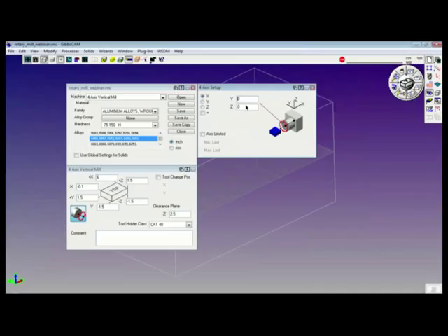Placing numbers in these values, for example, the Z, would give you eccentric rotation and may not be consistent with what you are trying to do. So my recommendation is to set these values at 0 and make the adjustment at the machine where you can touch off the top of the part and then dial down the center line and use that in your offsets on the machine. Some shops have predefined standards at that height.